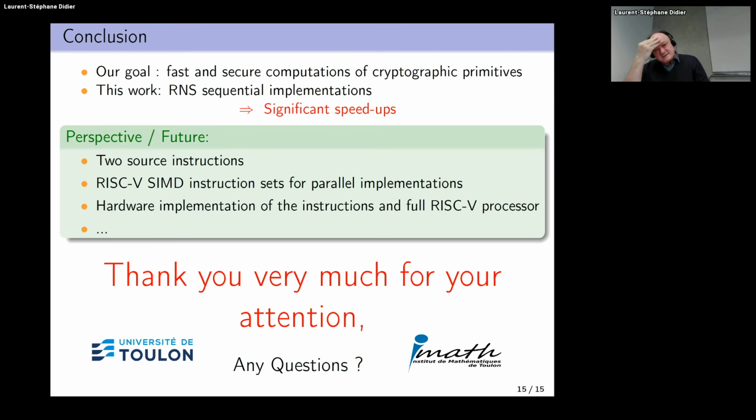If I understand the question, in NTT, in lattice-based cryptography, there is use of modular operation during the NTT step. Here it's slightly different because in lattice-based cryptography, the operands are, I think, 12 bits large. Here we are investigating quite large operands, word size operands of up to 64 bits. Maybe it can be useful for NTT, but I know that there are some other works that have been done in order to improve the NTT on RISC-V processors, and also in order to perform this modular operation specifically in the NTT. This work is for larger operands.